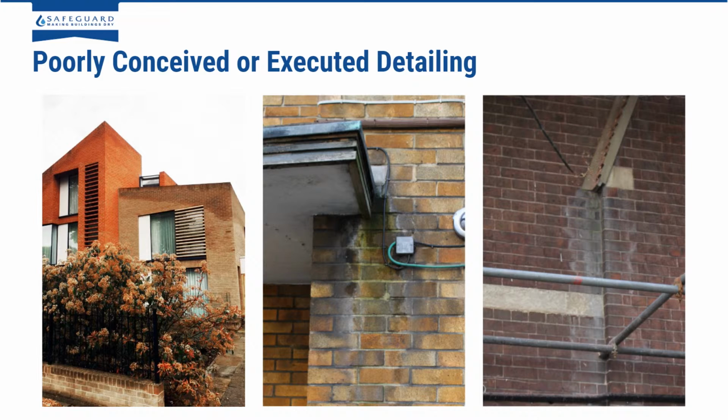Quite commonly we get calls from people who say they've got rain penetrating the property, and then we find out that their neighbour had a garage installed next door, and effectively rain has started shooting off the roof onto the wall directly, and so that's the reason. All they had to do was ask their neighbour to install some guttering on their garage, and that would fix the problem. Yeah, I've seen that exact problem where it was a pitched roof with no gutter, and the roof extended up to the boundary wall between the two properties. So the neighbour's rainwater was shooting off the roof and hitting the wall of the property next door.